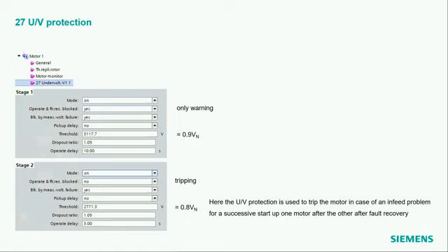I start manually the first motors, then the next motors, and so on. To trip the motors before I start them, I can use a simple undervoltage threshold, which I put to 80% of the nominal voltage, which then trips after some time delay, so that I can restart all the motors in a certain order.